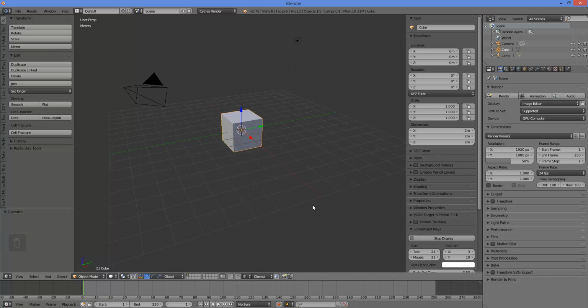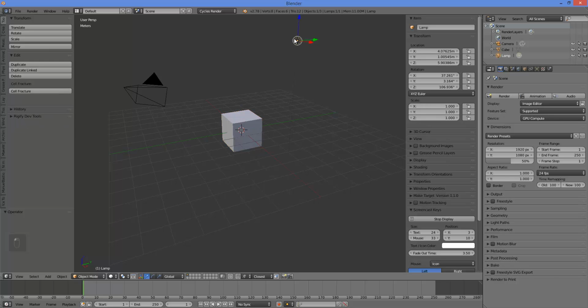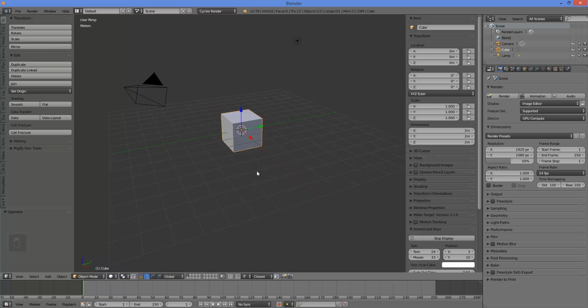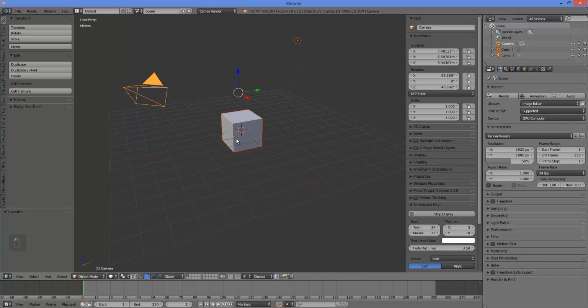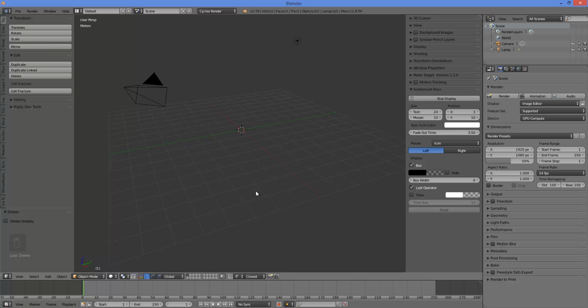At startup on the 3D view, there are a cube, a lamp, and a camera. You can select them with the left mouse button, or make a multiple selection typing B and dragging the box, or typing C, coloring the objects to be selected, and then pressing ESC. The outline of the selected objects will be colored in orange, and on the active object in light orange. On the active object of a selection can be applied materials, modifiers, and other functions. To delete an object or more selected objects, click on Del or X, then Confirm. To select or deselect all objects, type A.